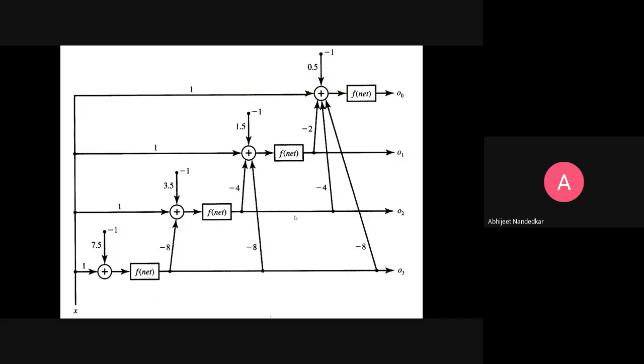Now this is the circuit which I was telling you about, that is the ADC. Here you supply some input and codes are generated. Suppose you apply 0 volt, then you expect it to give 0, 0, 0, 0 as the output code. When you apply full voltage, let us say 16 volts, then it should produce 1, 1, 1, 1.